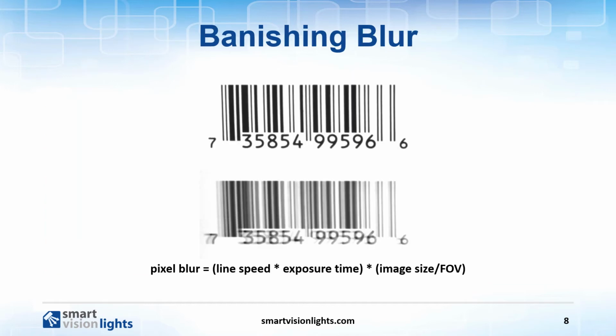A vision system's ability to freeze motion in an image is a function of how precisely and quickly it puts photons to the pixels. The faster the motion, the more challenging this becomes. A common goal is for each pixel of a camera sensor to detect one point on an object. If the point is moving too quickly relative to the camera's exposure time, it may be captured across multiple pixels. The resulting pixel blur causes poor image data.